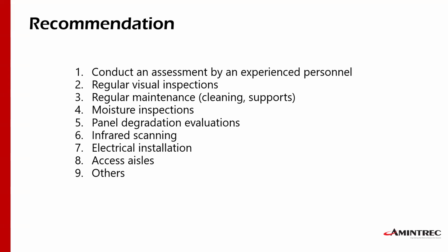Moisture is critical because over time, with degradation and temperature, the plastic materials tend to move and deform. That will allow water to go inside, whether to the modules or the bypass modules, and create corrosion. Corrosion will create a hot spot. A hot spot, throughout the time, will create arcing, and arcing is plenty of energy to melt the plastic and set those panels on fire.